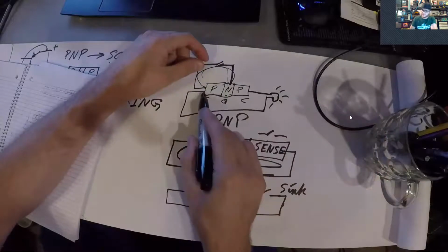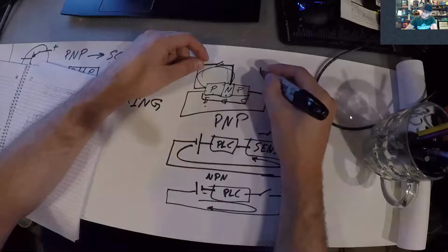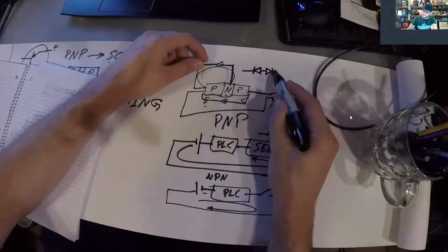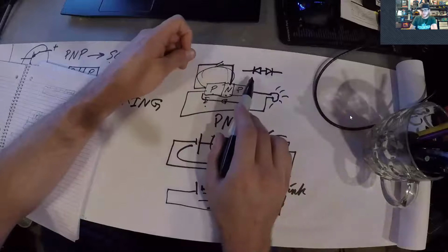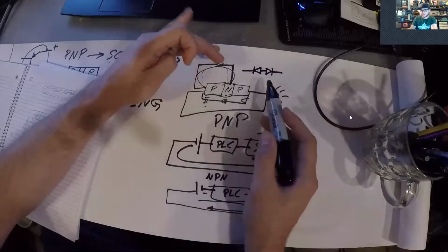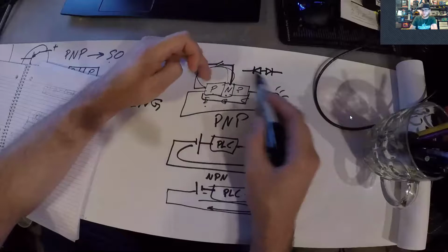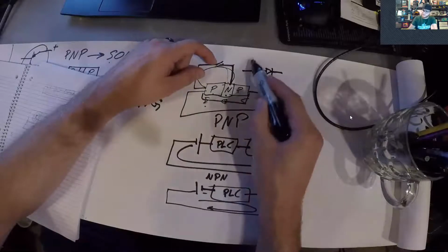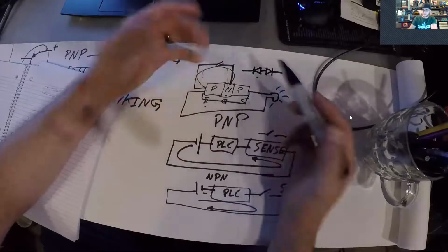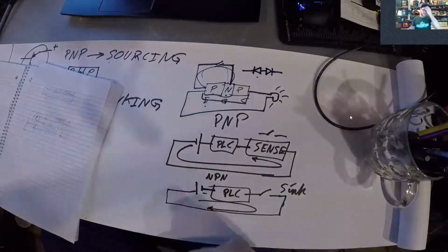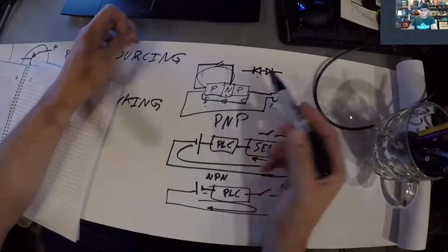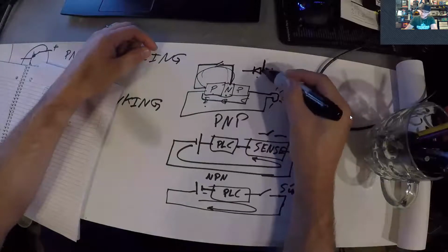But basically, this transistor is essentially two diodes wired in series. Okay. And so if you remember, we talked about early on, diodes are directional. They only allow current flow in one direction, which is the direction that the arrow is pointing when you draw this. And so if you have this circuit where it's two diodes facing in opposite directions, essentially you cannot have current flow through here.